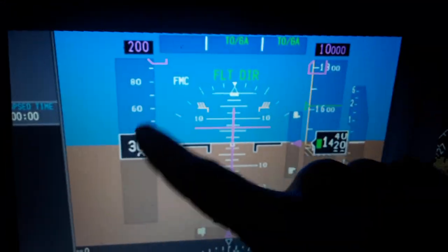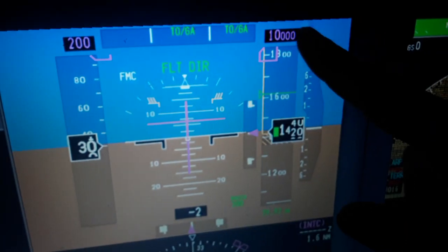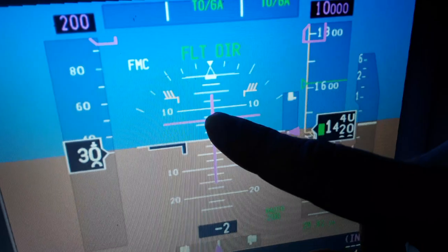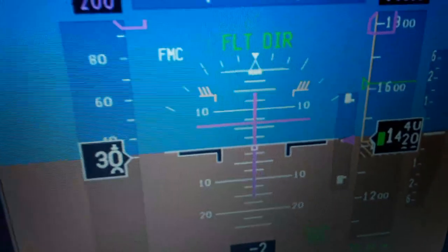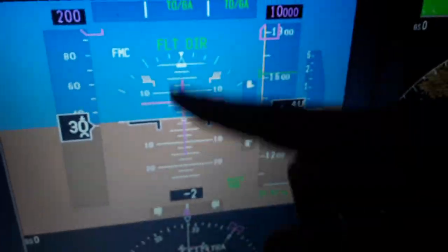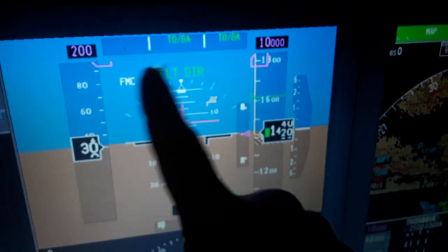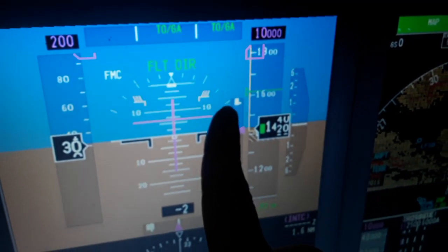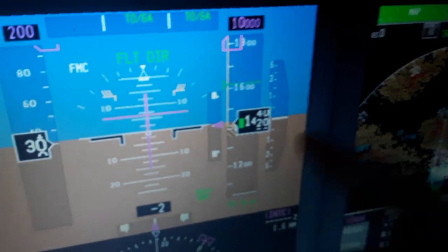On the display, you can see the airspeed indicated here, the airspeed tape, the selected altitude, the pitch ladder in degrees, 2.5, 5, 7.5, 10, 12.5, 15, 17.5 degrees, pitch up and pitch down, the bank roll of the aircraft as we fly, like 5, 10, 20, 30, 45 degrees left and right.